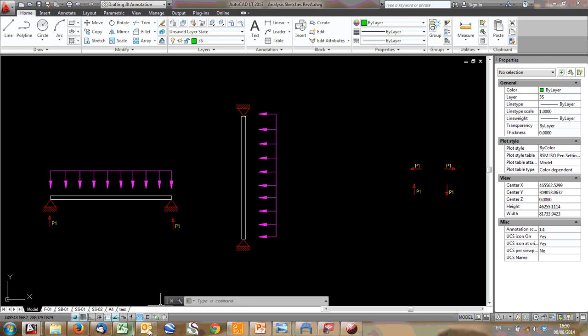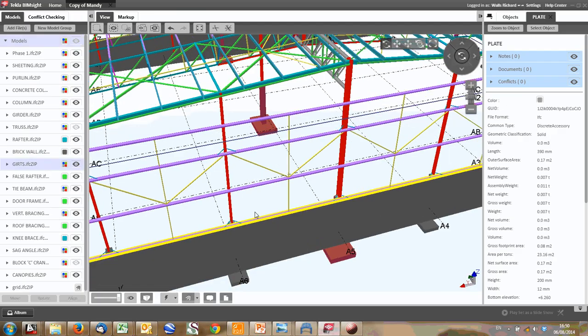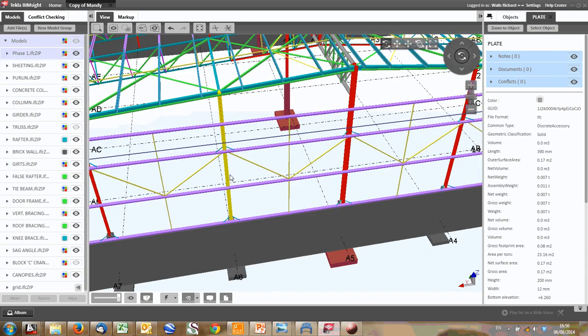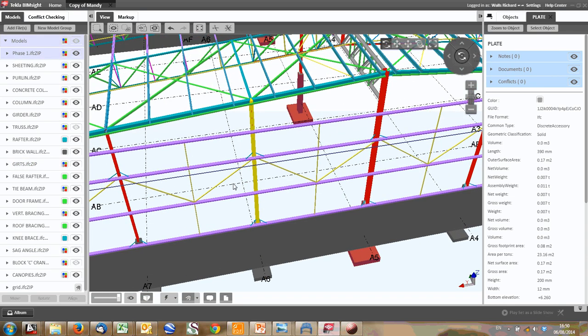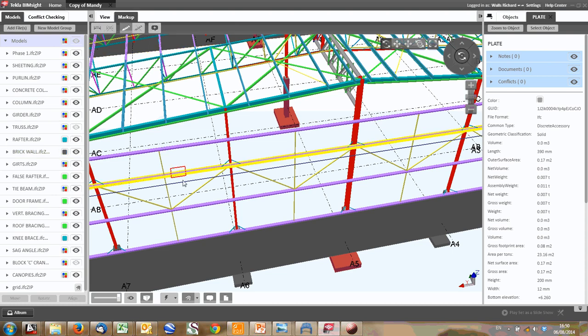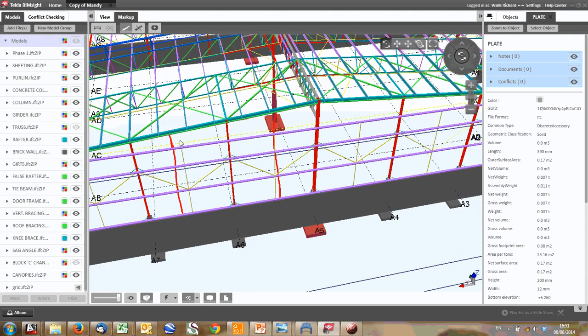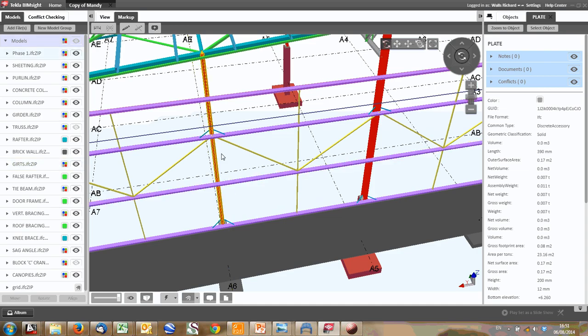We've got our pressure from the wind, which you need to calculate before starting. Then what area would be carried to this column? Well, this is halfway between each column. So if I mark it up, hopefully I can draw here. There you go. So an area like that goes to this column in the middle. So all this would sit on that column. That way you can very quickly get a load and design this column. You don't have to get lots of little point loads and have a very complicated analysis model. You can very quickly get an almost correct model. There you go. And you can design it.